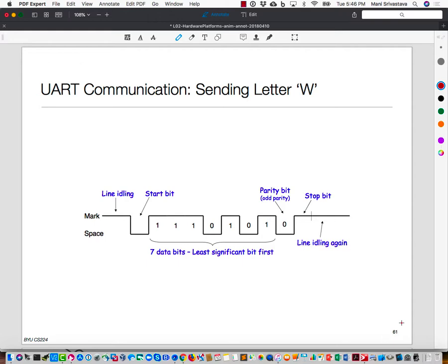Usually for UART you don't work this way, but for other serial standards, instead of a simple start bit, we have a pattern with multiple 0 and 1 transitions so that you can figure out what the sender's frequency was and then adjust your clock. But for the UART, you don't need to do that.